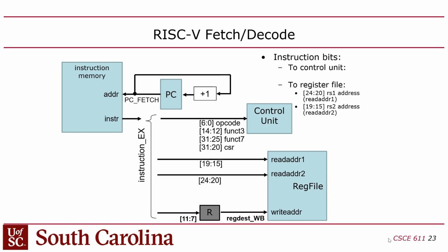Yeah. Now again, that's assuming you're inlining the register. You could create a register module. Some people in this class do that. They feed it into the register module and have an output. I just inline it. I just have one line of code, and in fact, I usually have an always_ff where I group all my registers into one always statement just for convenience. But that register is basically just an always_ff, a clocked assignment, essentially.